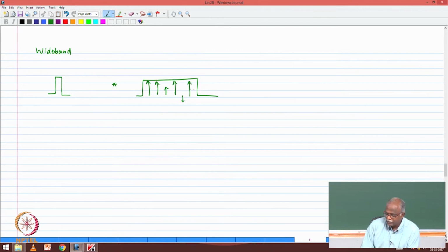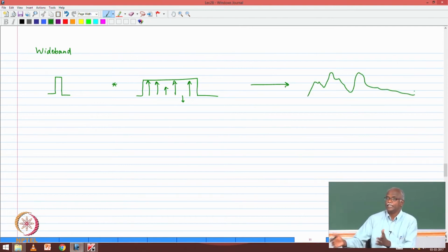Okay, that is the impulse response of the channel. So, the pulse is much narrower than this. So the convolution of these two produces for me a totally distorted pulse, and it's much longer in duration than what I transmitted. This is why an equalizer is needed, intersymbol interference.